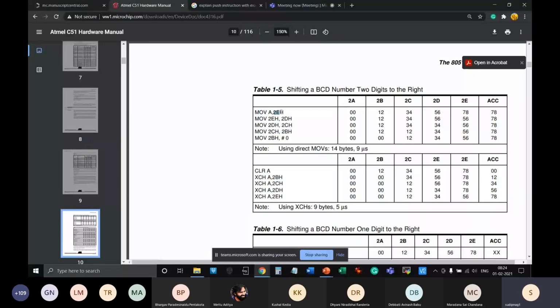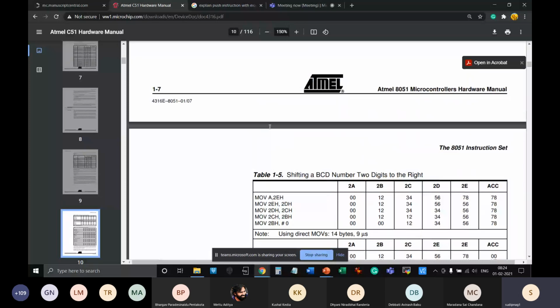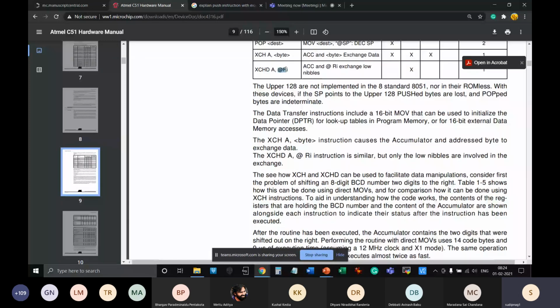And then you can see basically this is the immediate data. Although the hash is not written over here, preferably hash should be written. It depends on the assembler again. Sometimes our compilers and assemblers are intelligent enough to find out whether you should consider a hash over here or an @ symbol. @ means address, and hash means data.